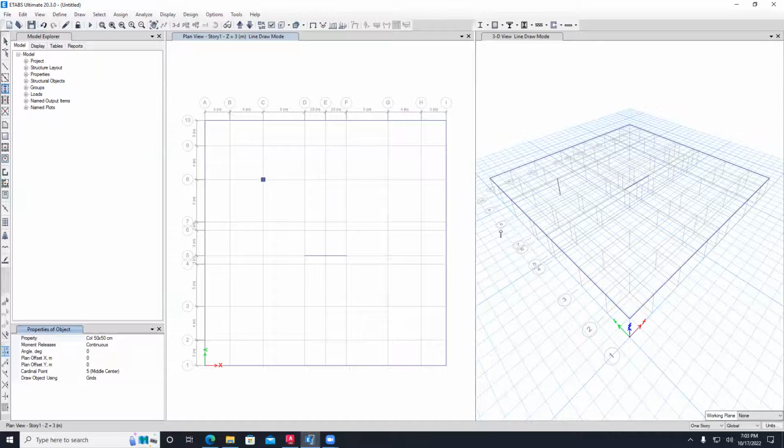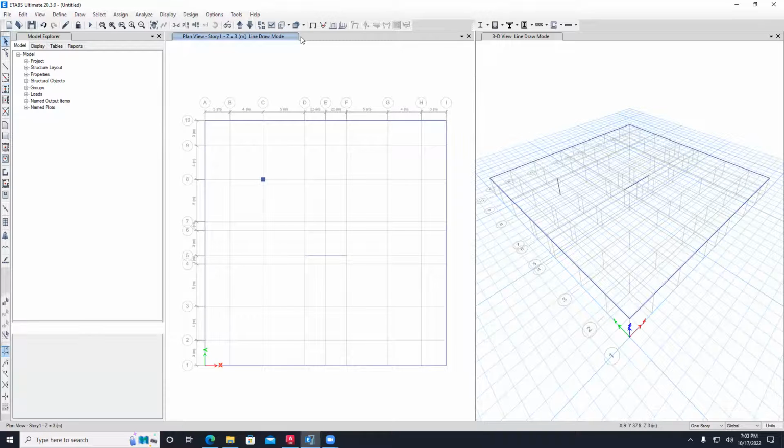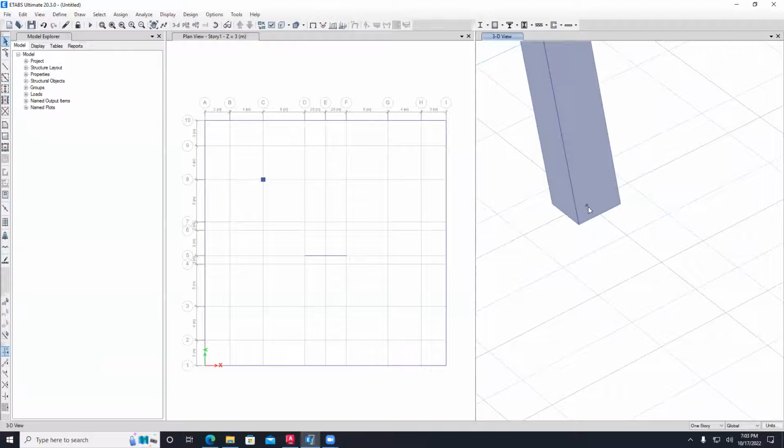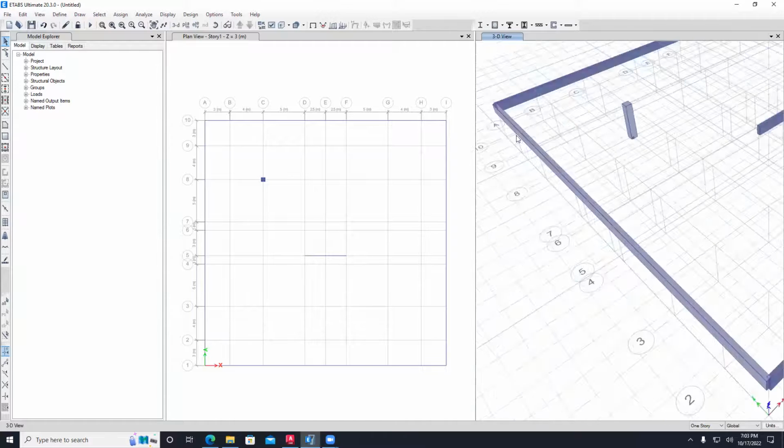I need you to look on the second screen. Everything that I draw here already knows that it's a column. So you put not only the joint, but also draw the frame element of the column itself. Okay. And if you want to look at this, we can extrude, escape. And let me extrude this to be, yeah. So here, can you see what happened here? He has the column and actually put a hinge underneath this column. So he did everything. He drew the column, he made the extrude, he put boundary condition. So it was very easy.